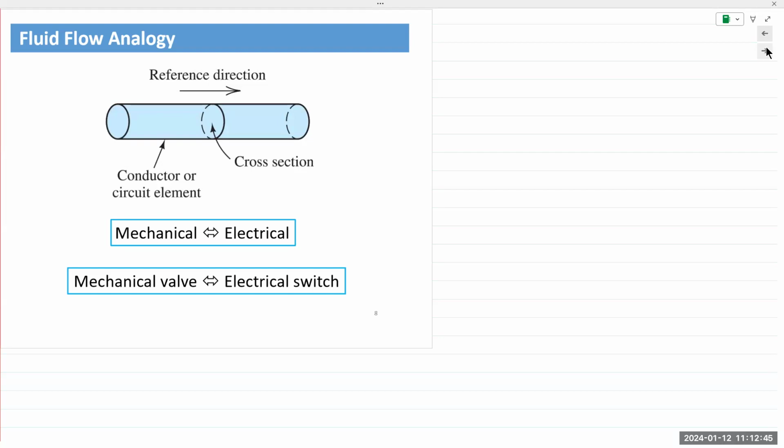The reason is you take a piece of wire, it has very low resistance, you stick it into the 2 openings, you now have a closed loop. Current can now flow through, but the voltage is so high, the current is so high that the wire cannot handle the amount of heat that is generated and it blows up. If you have a very thick piece of wire or a component that has high enough resistance that it can impede or slow down the flow of electrons, then you would not see anything except the component might heat up. That's it. But again, the point being, it needs a closed path for it to flow through.